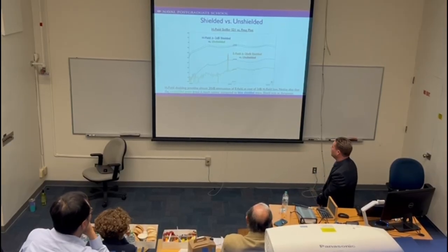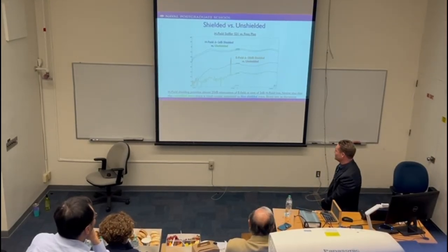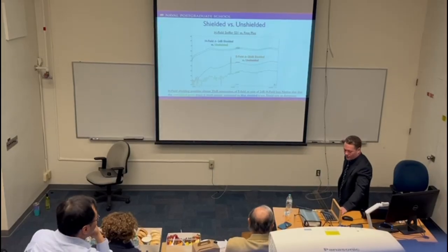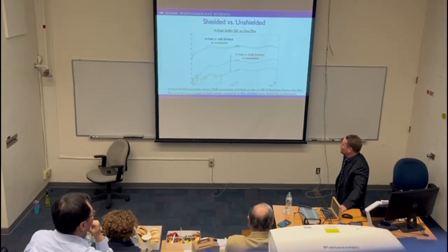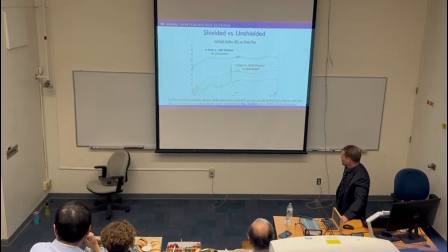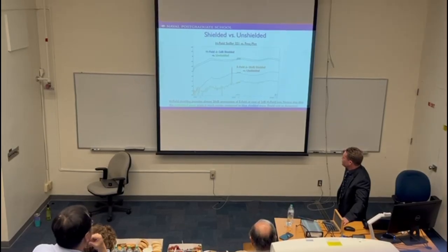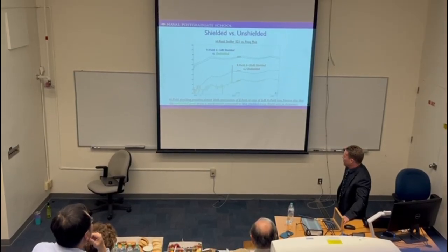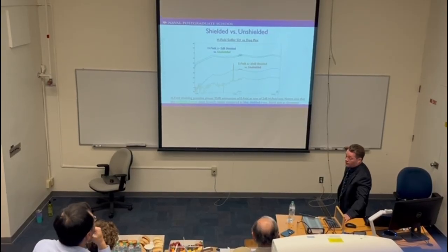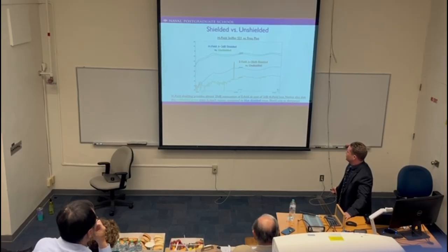It works very well. And Richard and I have been building quite a few of these. It's no joke. Sometimes you could accidentally solder and heat things a little bit too much, and things become interesting. But you can see here too that the unshielded green trace, you see how much noisier that is? Well, the blue shielded trace actually acts as a bit of a dampener on any of these resonances that are happening. You can see how much cleaner that trace is with the blue.